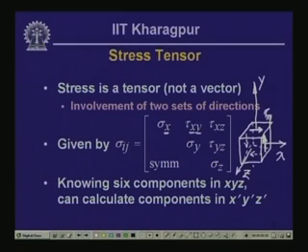That is because the outward normal on that plane is acting in the negative y direction when the force because of which this shear stress arose is acting in the negative x direction as well. So, if both are negative, then we are not going to consider the sign, and if both are positive, then also we are not going to consider the sign. So, tau xy will be the same as tau minus x minus y. Okay.